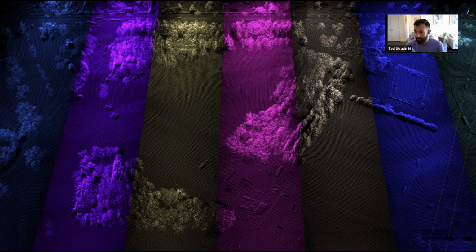If you don't do this, this can really vary by the sensor, because some sensors scan differently. So this is an example from DJI L2 data. That uses a very different type of scanner, and the mirror, as you can see, oscillates and creates this pattern. So if you don't do this cutting and cleaning of the data, then you may have less than optimal results, because there's just so many points built up there.